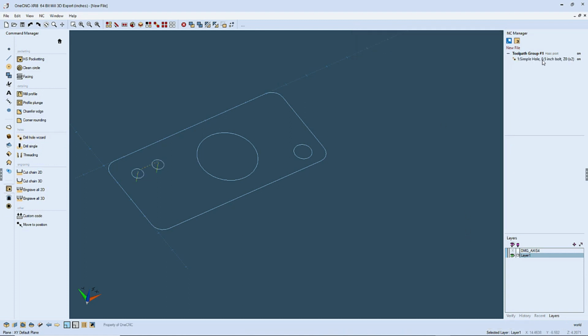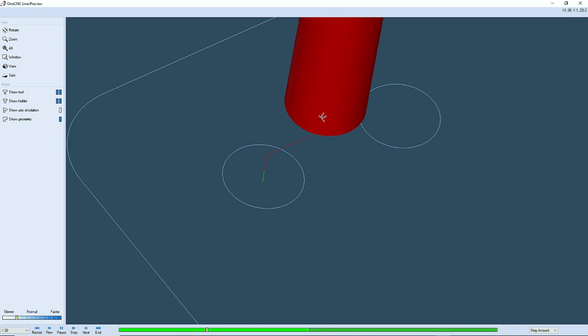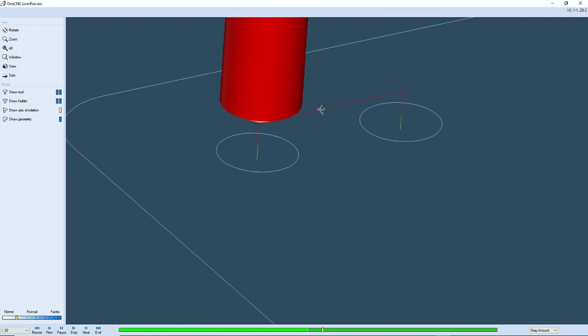And then within this one command, it's actually performed 2 machining operations, 2 hole operations. We've spot drilled, and we've also performed the PECK cycle. All right, so if I quickly preview this just to verify that, you just right click and preview toolpath, and there's our spot drill. And then here is our 1/2 inch drill.